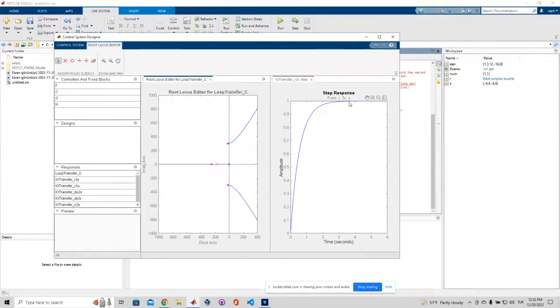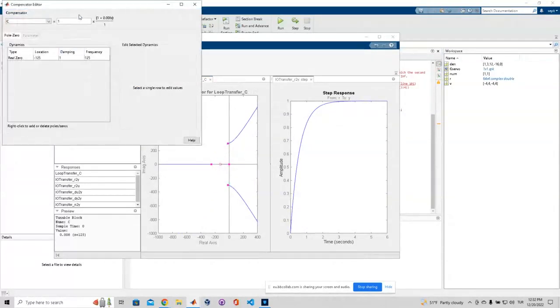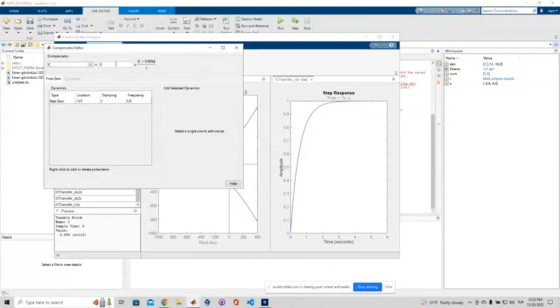Let's say we add it here, and we see the step response, and you can shift it to see how the step response changes. In here, you can modify your system. Let's say make it 10, so you can see our step response. It's not a very good step response. It's not stable. Let's increase it to 20.